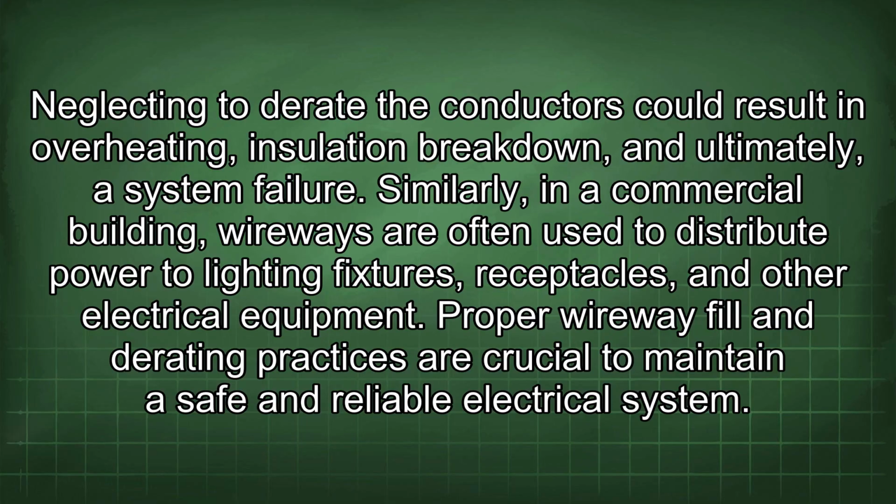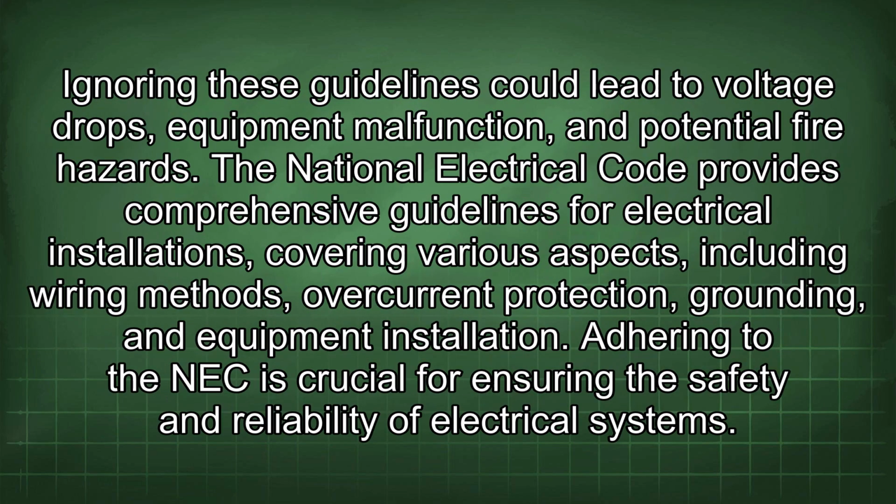Similarly, in a commercial building, wireways are often used to distribute power to lighting fixtures, receptacles, and other electrical equipment. Proper wireway fill and derating practices are crucial to maintain a safe and reliable electrical system. Ignoring these guidelines could lead to voltage drops, equipment malfunction, and potential fire hazards.